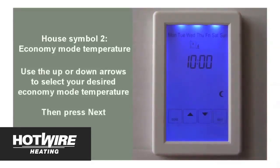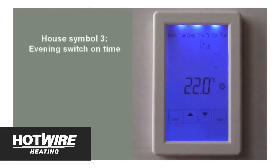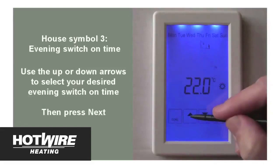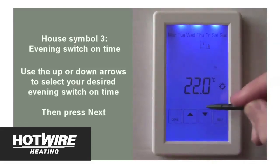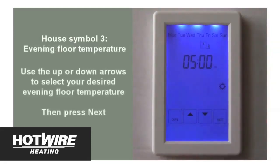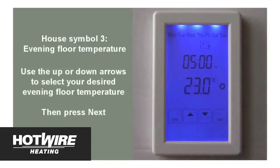Then press Next. The house symbol displaying the number 3 and a person returning will show at the top of the display. This is your floor's evening switch on time. Like before, select your switch on time, in this case 5 o'clock in the evening, and press Next. Then once more select your desired floor temperature, in this case 23 degrees, and press Next.